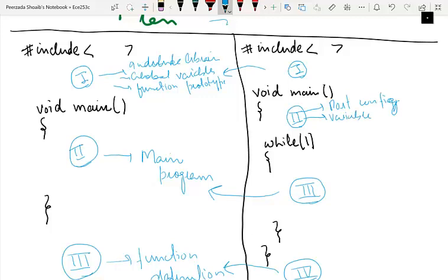This will be more clear when we write some programs or when we do some examples. Okay, so that's it. Embedded C program. A typical embedded C program usually has 4 regions. Region 1 is used for the same things, including libraries, global variable declaration, function prototypes, and other things. Region 2 are those things which go inside the main program but are executed only once, like configuring the port as input or output, variable declaration, and other things.